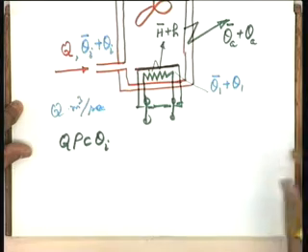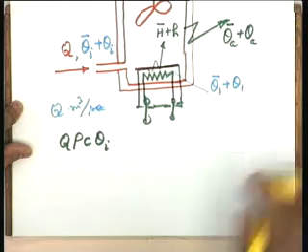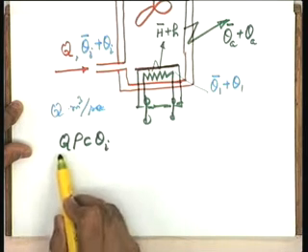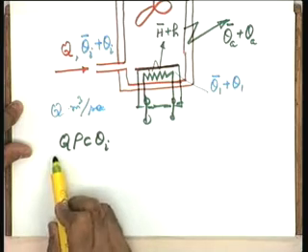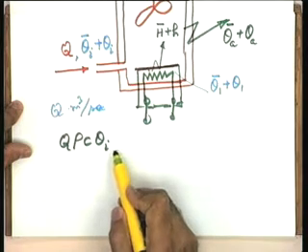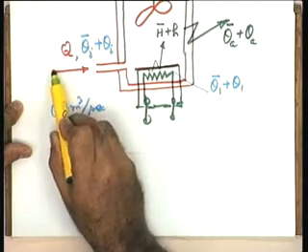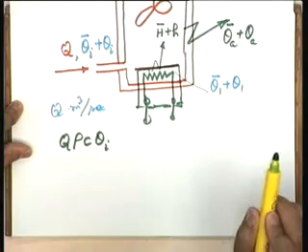Otherwise, theta I bar equations I will simply take out from the total equation and get the perturbation model. So, here I am writing theta I. So, it means it is the variation or perturbation in the heat flow rate, and units will turn out to be joules per second. This is the heat flow rate from this particular inlet point.